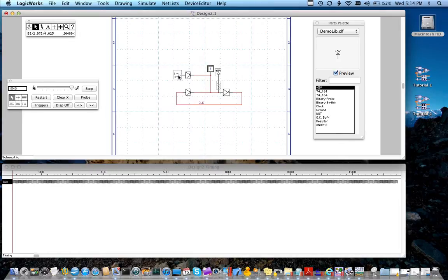Basically, the feedback causes the oscillation, and we can make use of it when we want to construct our own clock. Now, one of the other neat features when you're building a circuit to check out the simulation is that there is a probe, and if you click on this over here, you'll get a probe, and it'll show the values wherever you put the probe down. It's a neat way of checking the values of a signal without having to put a permanent probe. This is sort of like a temporary probe, and you can probe around on the circuit. It's quite handy.